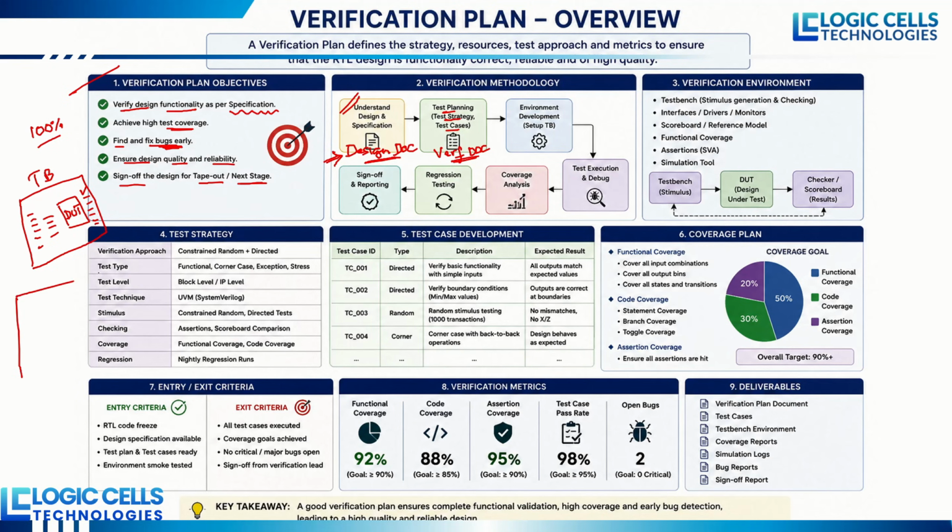Remember, your test bench can have a stimulus generator, let's say a generator, and here your DUT sits. It will take the input from the generator and give the outputs, and internally you may have a checker as well. It will check your DUT outputs against the standard outputs. So your test bench will have a data generator, a DUT inside to verify, and a checker.